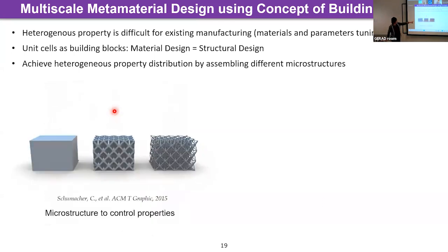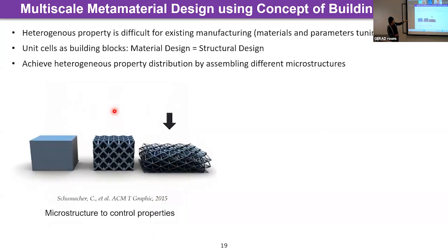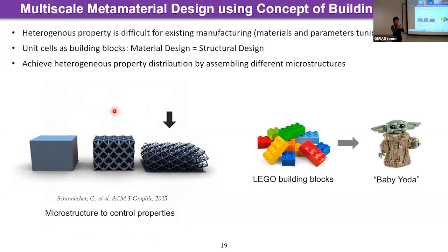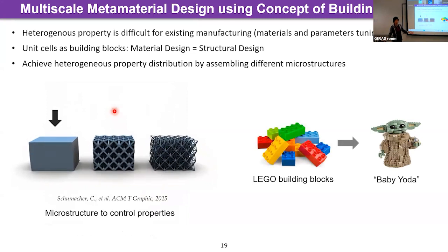So this is an example of a system with negative Poisson ratio. You can see, when you apply load, how it deforms, it has some interesting behavior. In general, a system with negative Poisson ratio can lead to very good energy absorption behavior. So you can imagine you design a bumper, right? Or a helmet. Those structures are very desirable because they can absorb the energy.